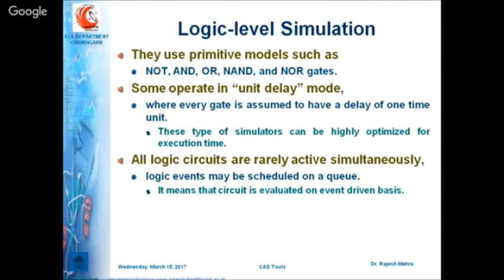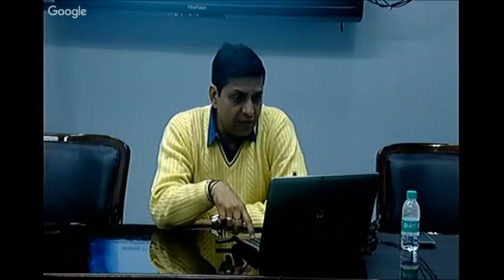For example, in the first positive clock, partition 1 is going to work. When the working of partition 1 is complete, then in the second positive clock, the second part is going to work, and in the third positive edge of the clock, the third part is going to work. So after 3 clocks, you are going to get the output of your design. So your logic can be scheduled, and a queue can be generated, and different sections of your design can work at different time intervals based on the clock. In this way, your software should be able to provide such kind of simulations.